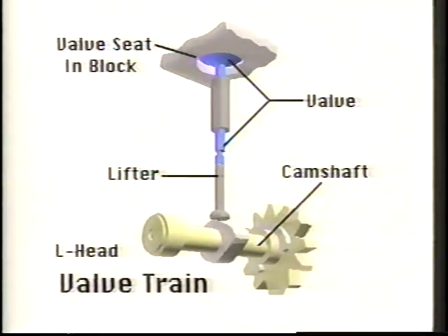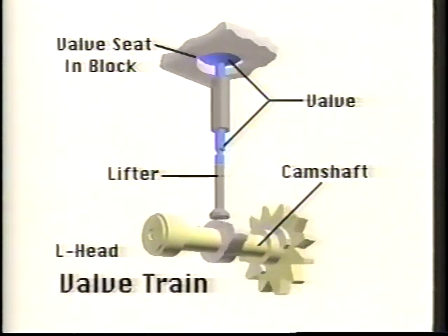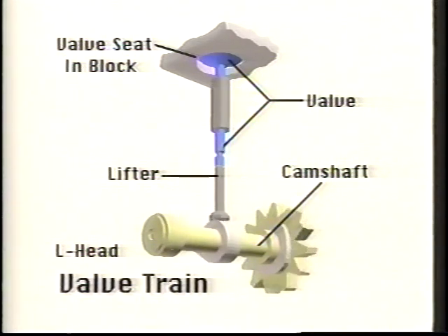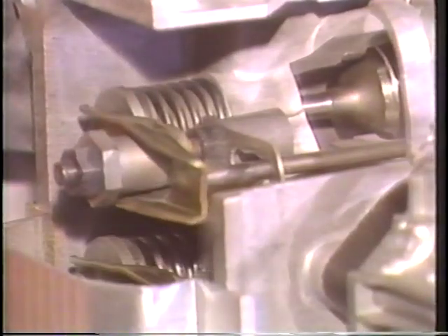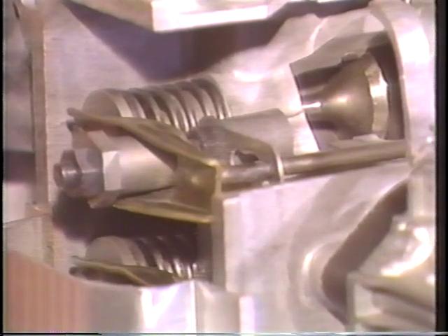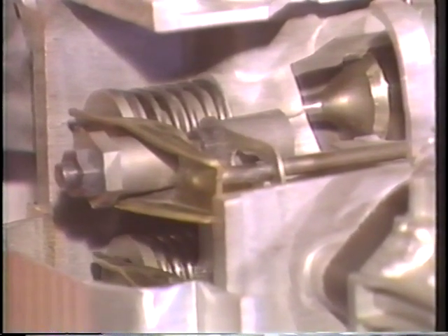Valve and camshaft locations are another method of identifying a small gas engine. Early engine designs position the camshaft and valves in the block, termed an L-head or flathead engine. The head was simply a lid over the cylinder and did not hold other parts. Newer engines tend to be I-head engines, which locate the valves in the head and the cam in the block.